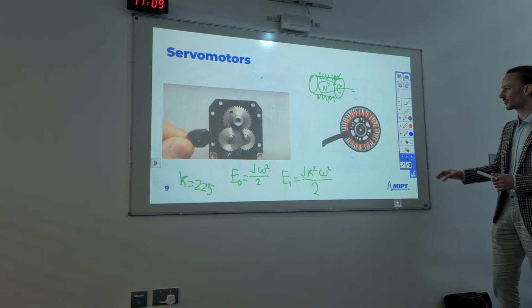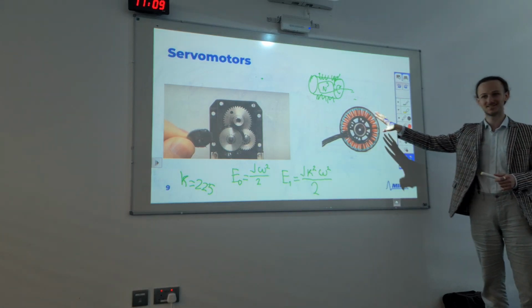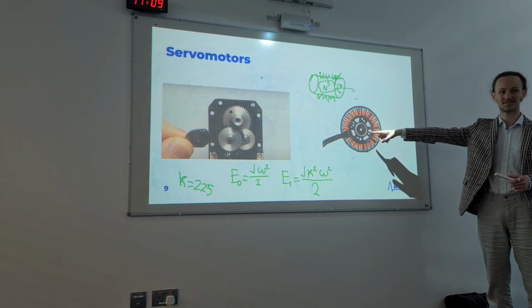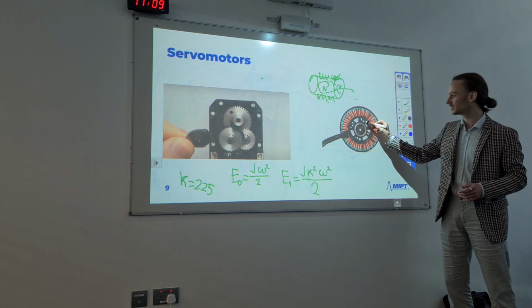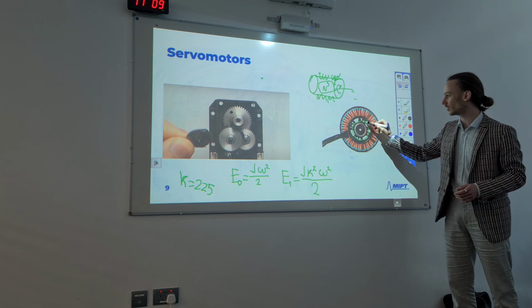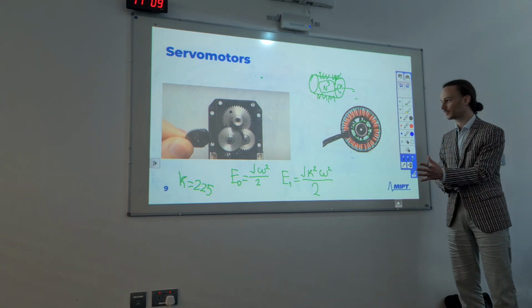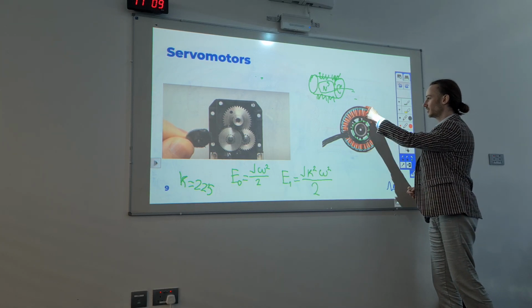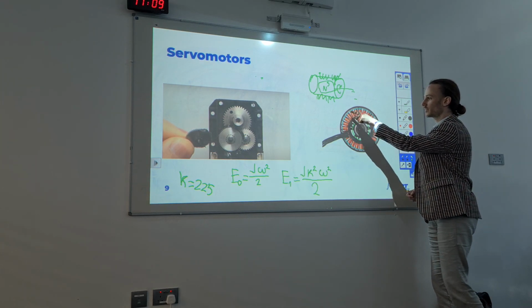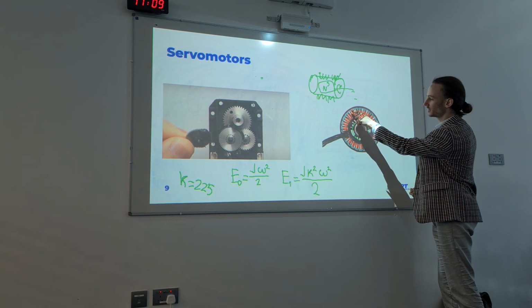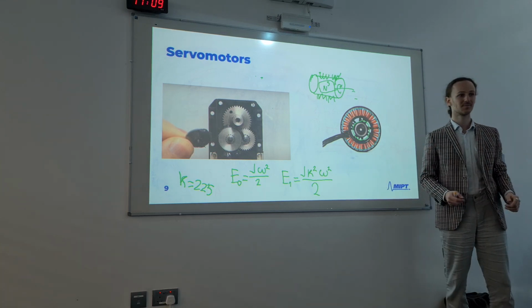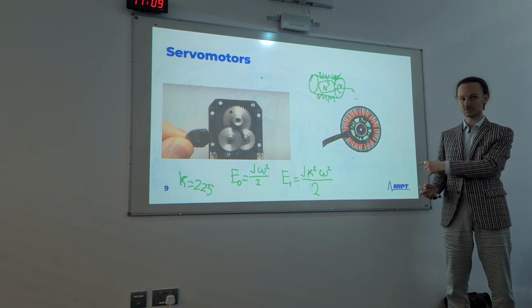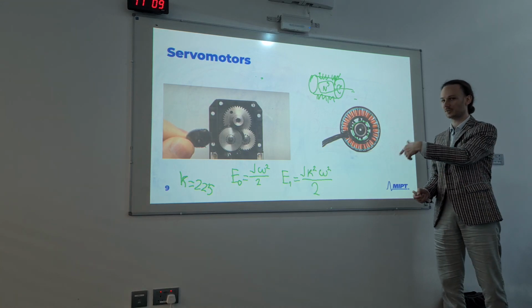And this motor is just different. The rotor here is on the outside, and the stator is inside. This part is fixed to the detail, to the body. And the external part, this thin cylinder, this thin circle with the permanent magnets here, is the rotor. These motors are called outrunners because they have an external rotor.